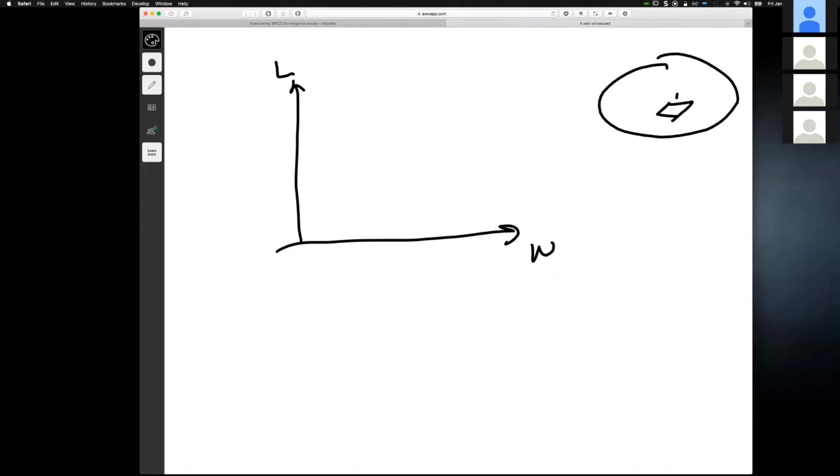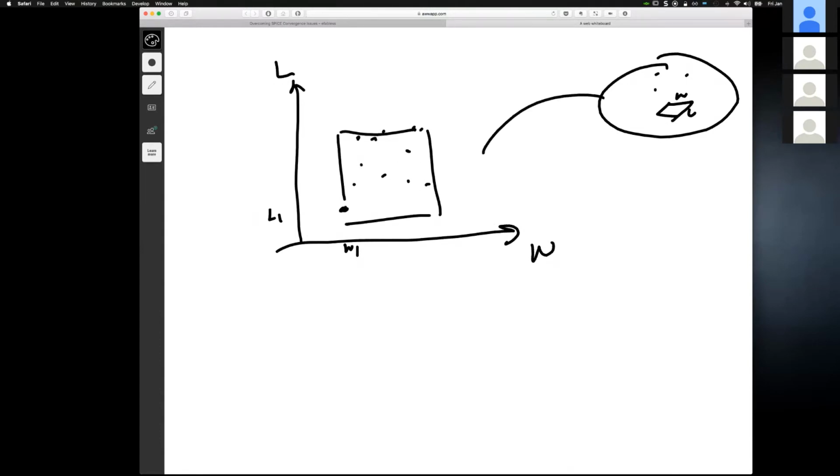They will have W's and L's in arrays, and then you will end up with points on this chart. They will say, here's W1, L1, okay? And then they choose certain areas, and you say, okay, I'm going to manufacture these on a wafer and then measure it, and create the transistor model, okay? Fit it to that.